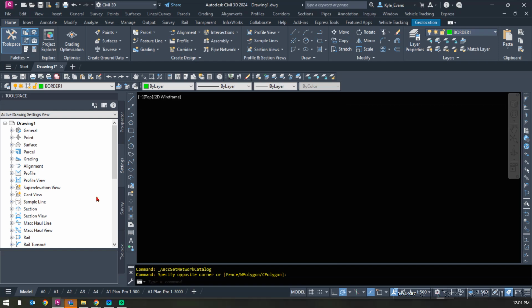The next thing, I don't think I've given you or maybe I have. We'll find out here in a second. So in your tool space, like I said, there's a ton of setup that needs to be done before we can draw anything. Who wants Civil 3D to monitor pipes for them and tell them when they violated something? Some of you look like, I don't know about this. Right? I let Civil 3D monitor some very basic information about my pipe, minimum slope. So am I violating the minimum slope? Am I violating cover? Am I violating this basic information?